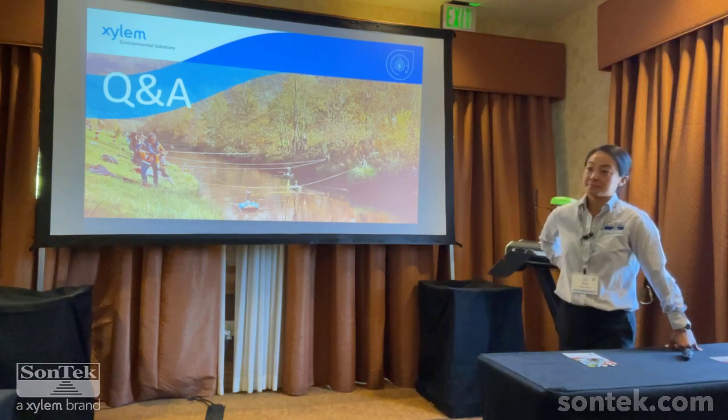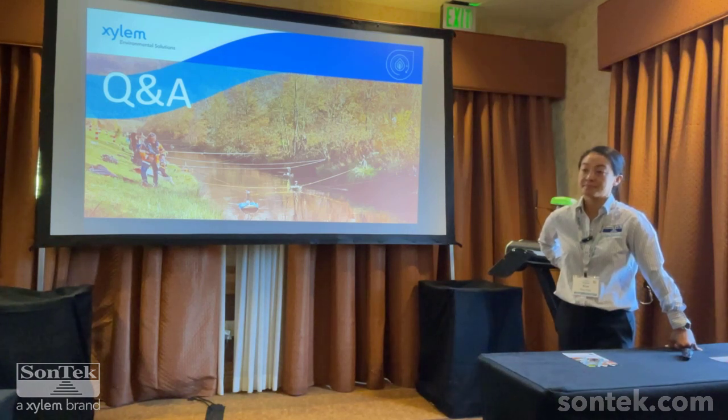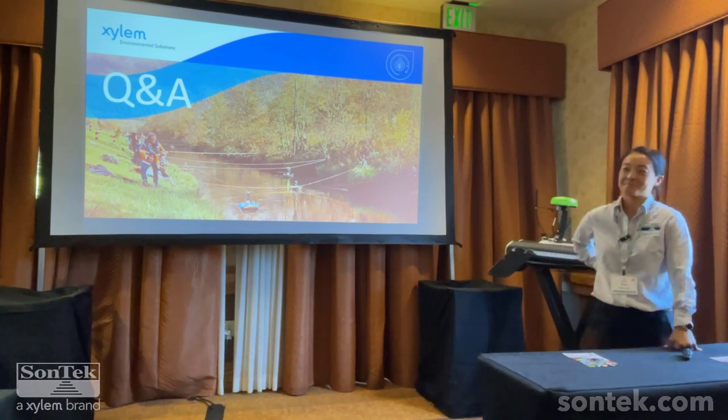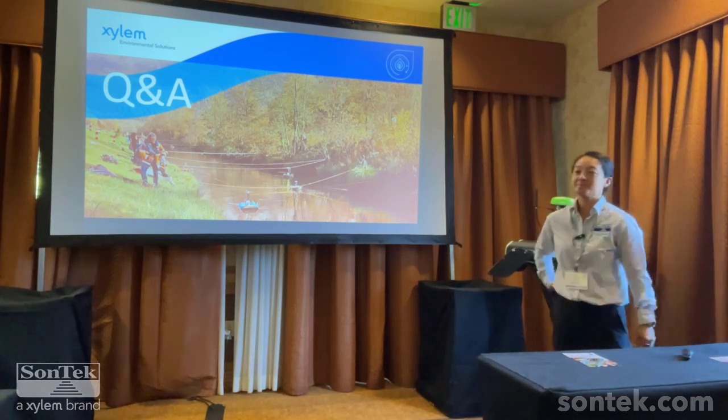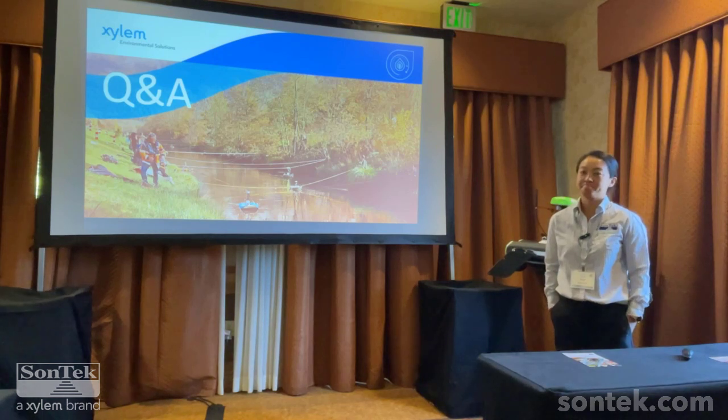If it passes the compass calibration, it doesn't necessarily mean it's good. If you pass the compass calibration, put it in the water and start measuring, and then you see compass errors, that means it calibrated to that location on the tripod, and now it's in a much different environment on the river, so it's throwing up errors. So you would know at that point that it's not calibrated. Yeah, in our software, we have compass alerts and errors. Okay.